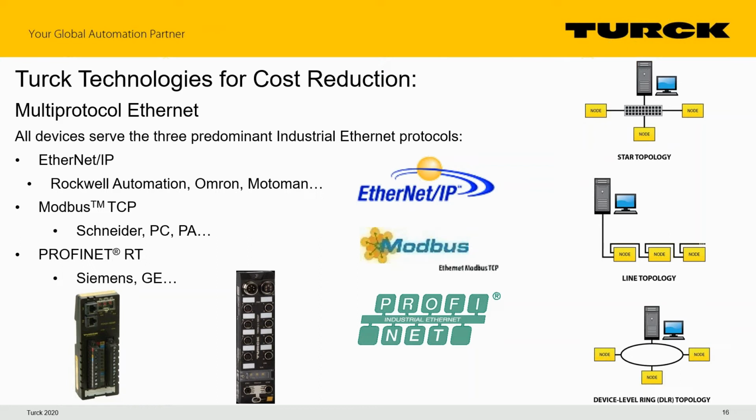So we actually have customers where two machines are meeting, say it's a conveyor system, and the two PLCs will read the sensors at the exit of the upstream and entrance of the downstream machine so that the PLCs don't actually have to communicate together. They're just reading those sensors. When there's a box upstream, there's no box downstream, both PLCs can turn their conveyor on and pass that box down. It really simplifies some of the interface between machines.